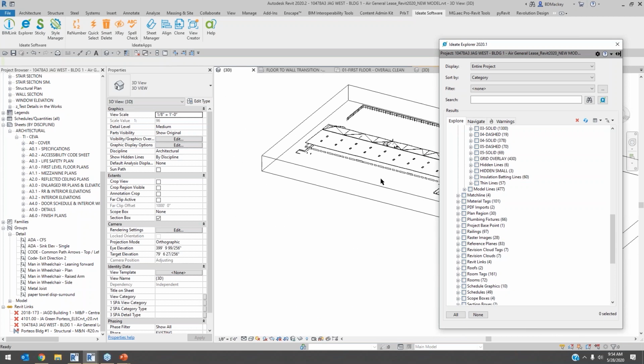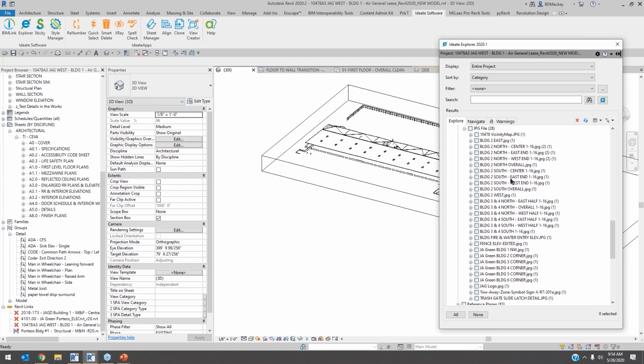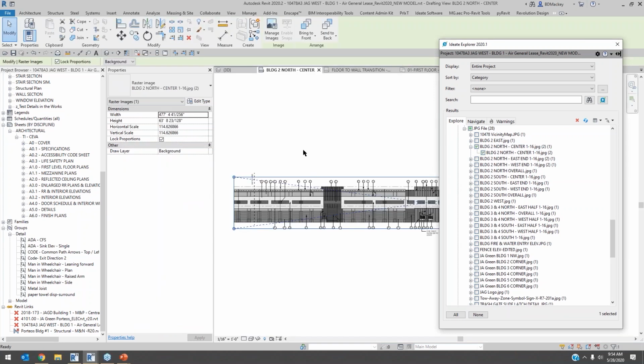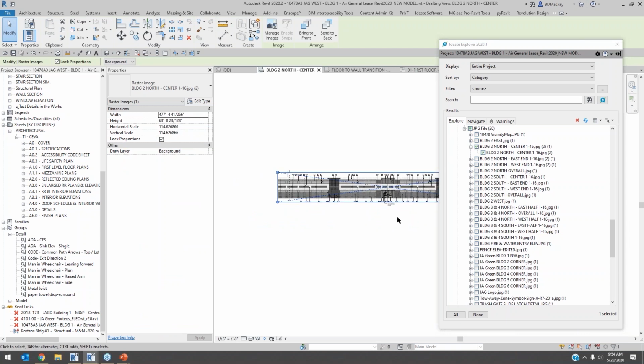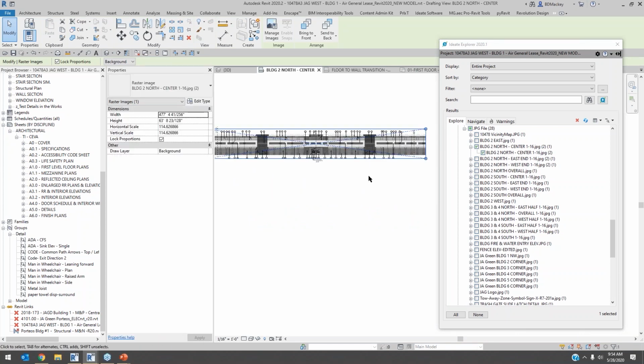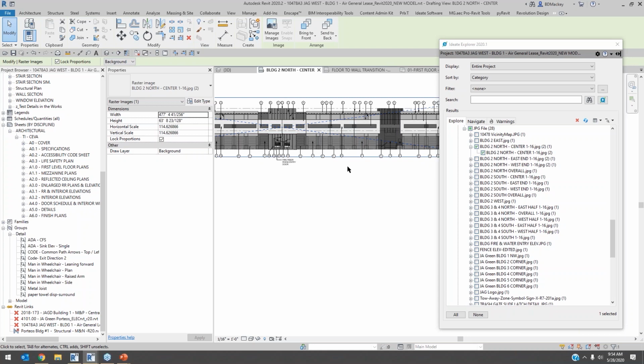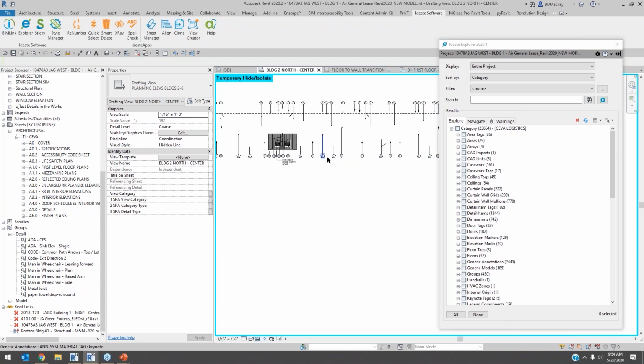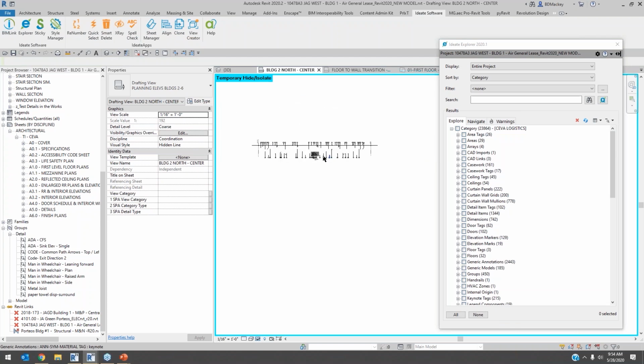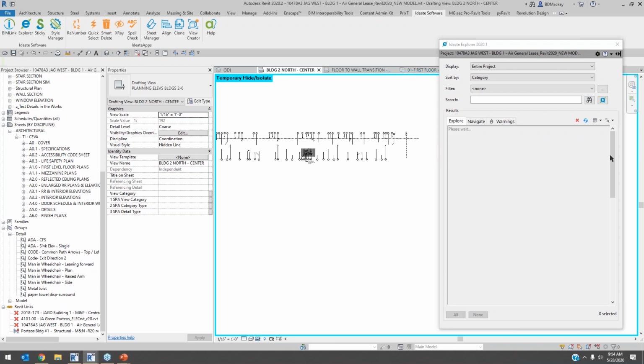And a lot of times I'll do it from a 3D view. I'll do it from plan views, but just really being able to start coming through here and looking. You know, the other one for me is, why is there 28 raster images on here? What do we've got going on? Well, let me double click that one, and let's figure out where that raster image is. Okay, so this is a preliminary schematic project for our client. So somebody dropped in a raster image in the elevation, right? Let me just go hide it with the sunglasses, and you can see that it's going to pretty much be the entire elevation, because I'm pretty sure this one was done in SketchUp to start with. But you can start going through and really seeing what's going on inside of here and just quickly see what's going on in your model.